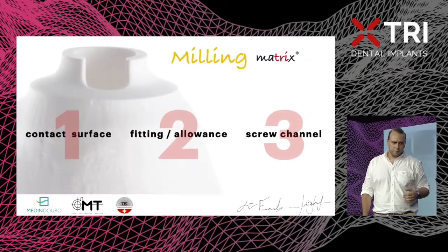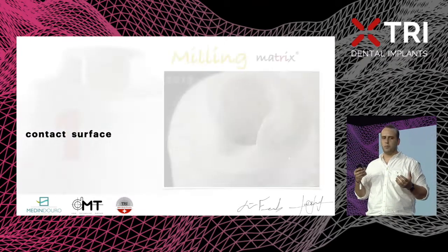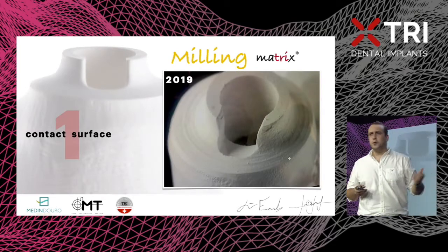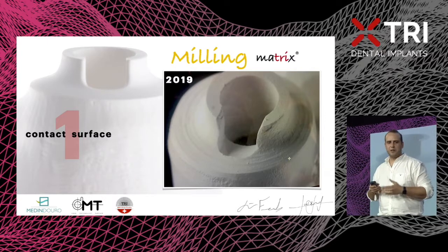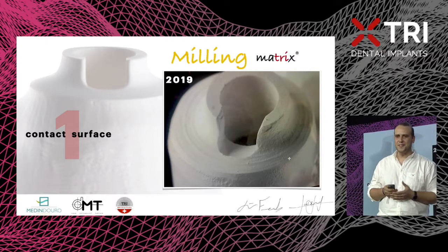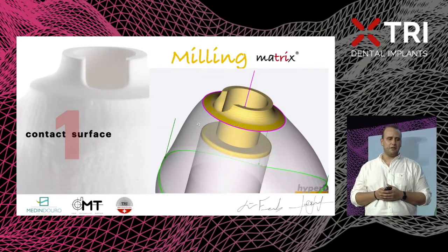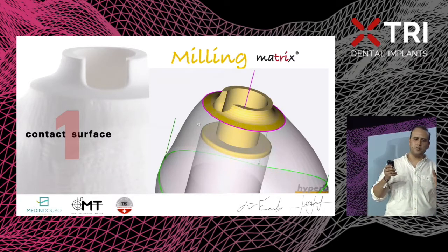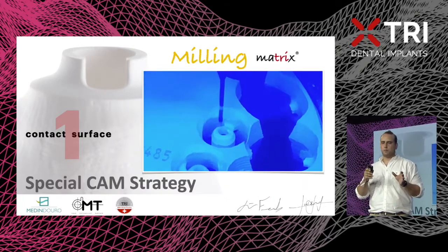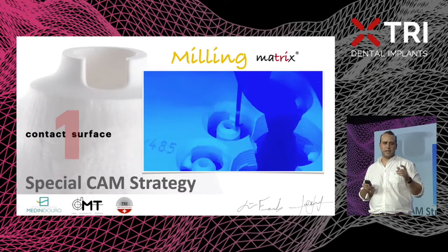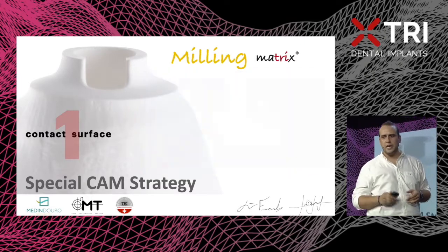In the first point, I will show you the contact surface, one of the most important parts in the crowns. 2 years ago, more or less, we started to mill just an STL file, and the results were not so good. But after that, we developed and improved every time a special strategy to mill that connection. And what we do, for that perfect surface, we use a round drill a lot of times. I will show you a next video about